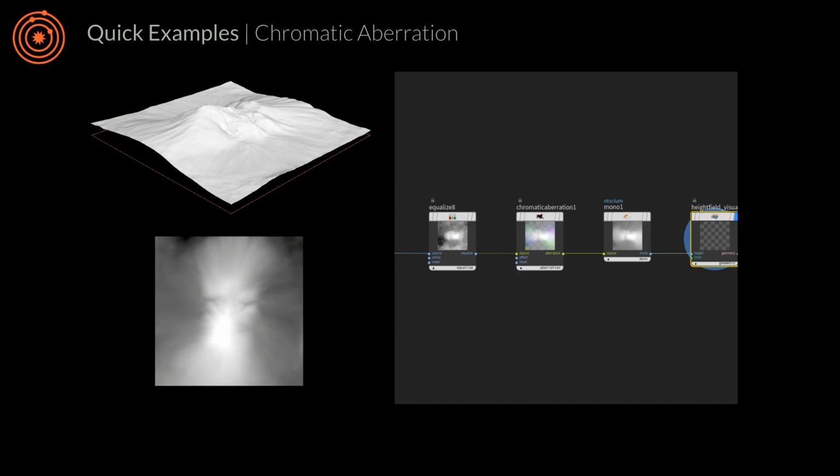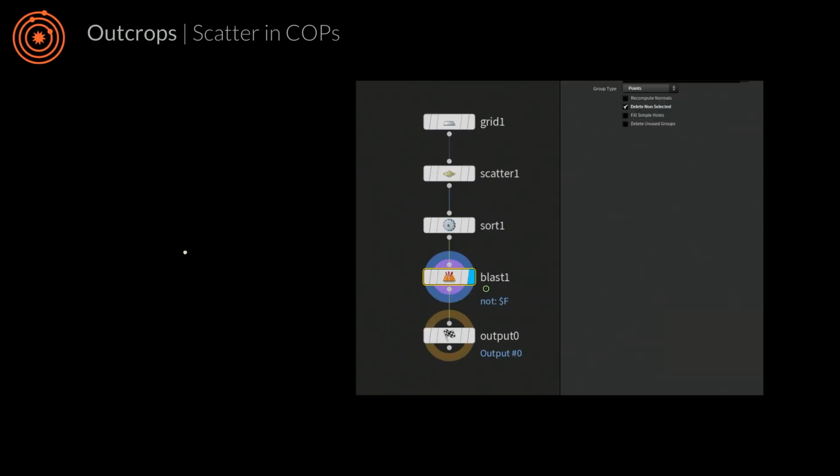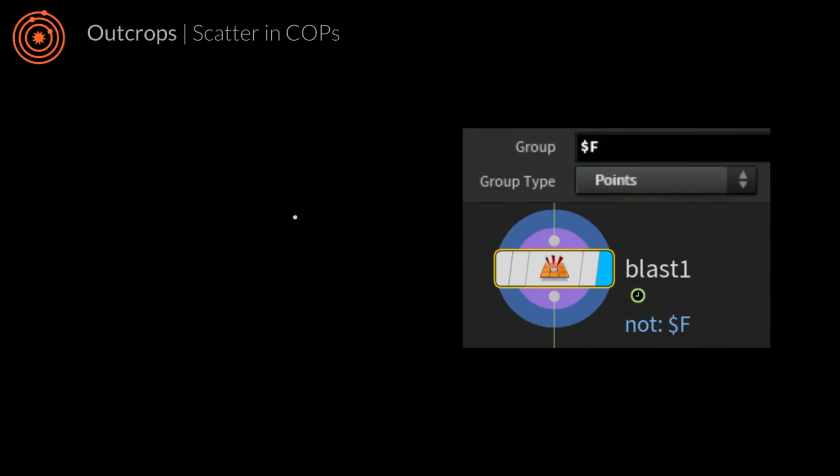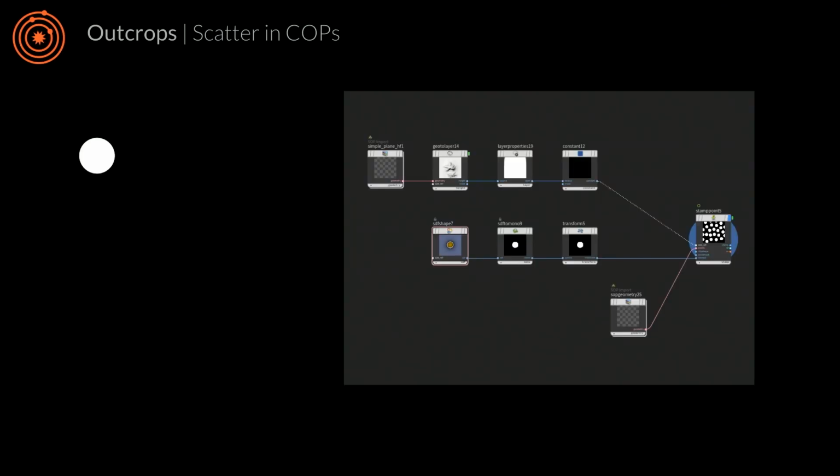So if I play my play bar, that point will just jump around, because I'm killing all the points except the one that corresponds to the current frame number. Now you can see our point is running around, and if we go back to Copernicus level, you can see that circle is just alone, because we're not running our network right now.